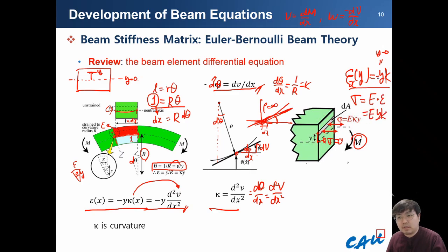I mentioned that although we added the minus sign, we don't change the sign in the upper part due to the elongation. But in the below part, due to the minus offset, the stress has a different sign but the same magnitude. This part has positive stress, or pulls, and this is the negative direction.